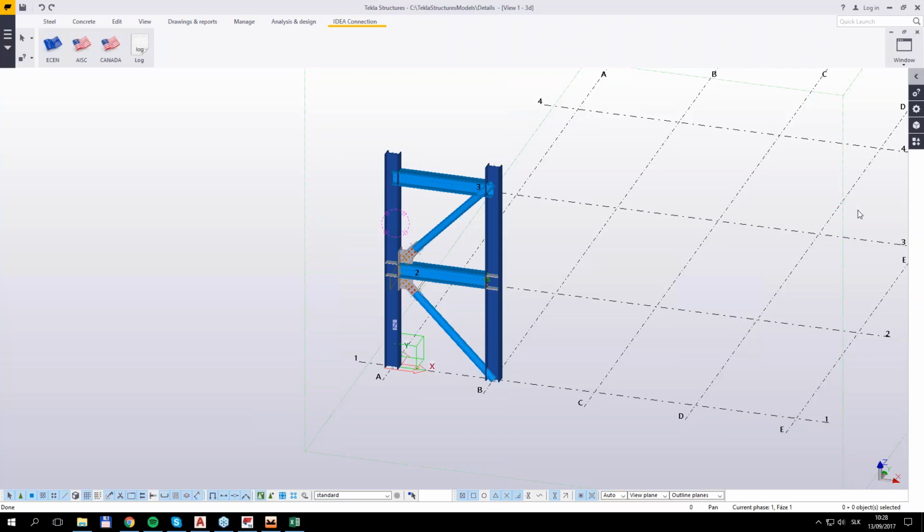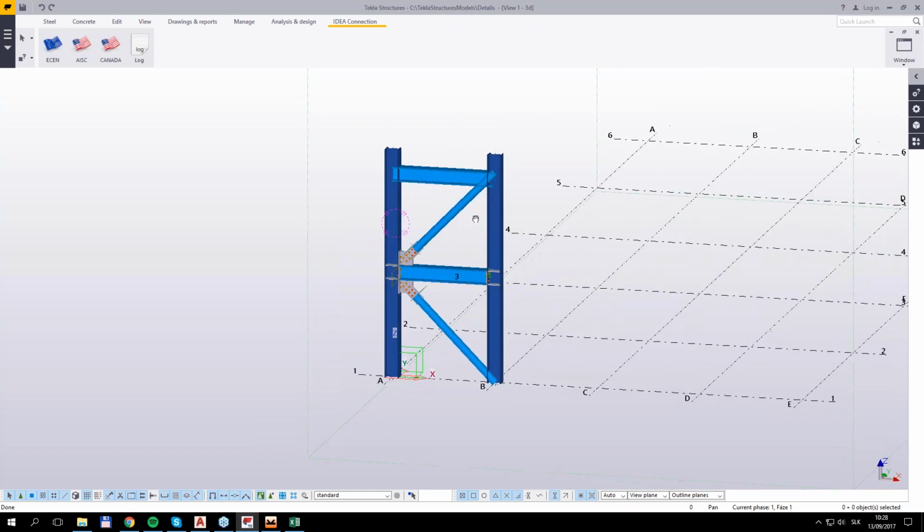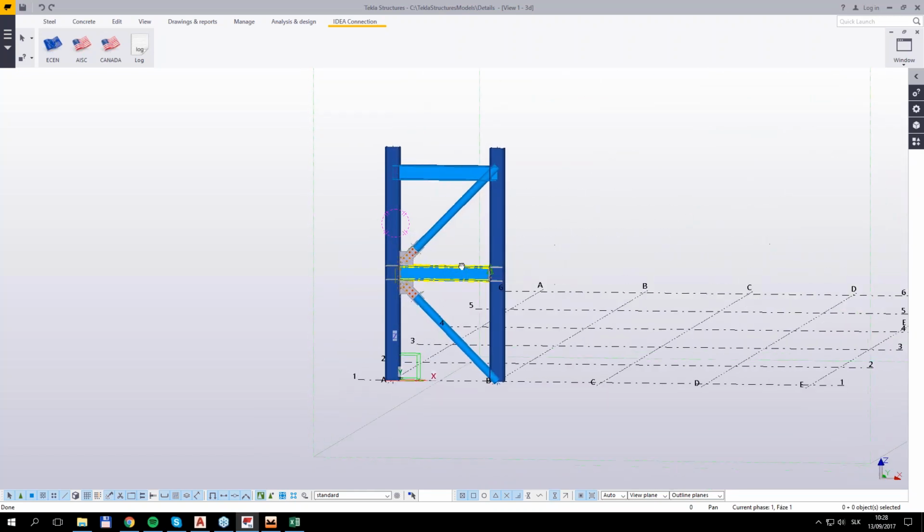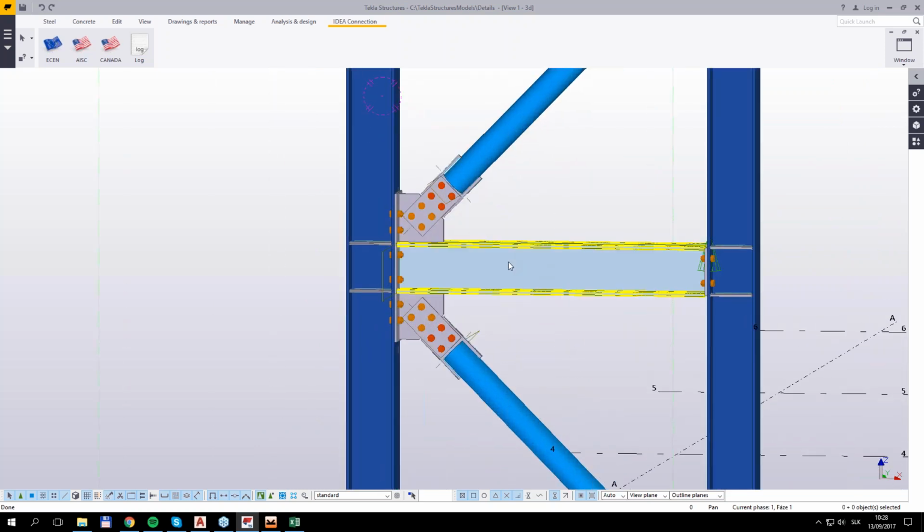Okay, thank you, David. And I hope you see the right screen with Tekla. I'm here today to present an example and workflow from Tekla Structures to IDEA StatiCa. So we have a simple framed connection with 2 braces, and I can easily export it by the Europe flagged icon. I have integrated IDEA Connection into Tekla. Feel free to look up the steps on our website or in the Resource Center. So let me start the command.